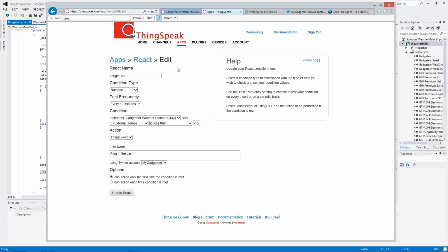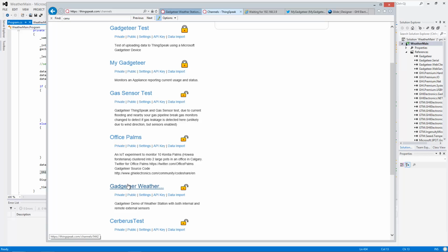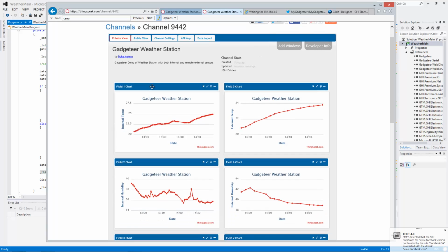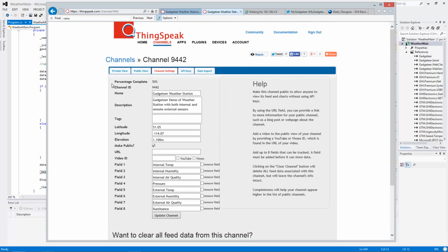They're great. To set up a ThingSpeak site, you register for ThingSpeak, and then you go in and you create a channel. I've created a number of channels for different experiments that I've done over a while. And so this is my ThingSpeak channel for this. You have these different channel settings, descriptions, and then there are 8 fields of data that you can send up, which makes it really great. It's really easy to use.